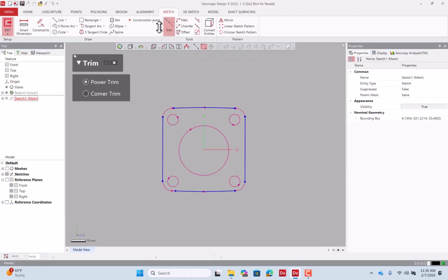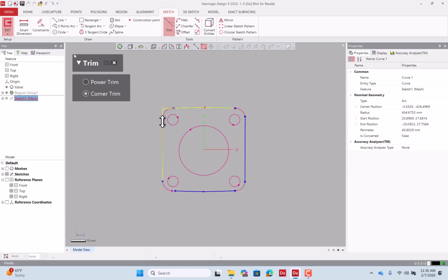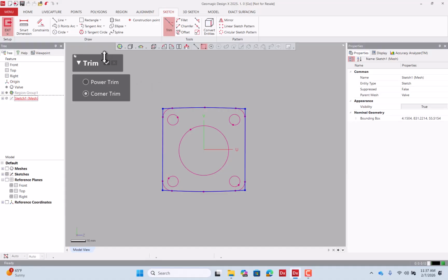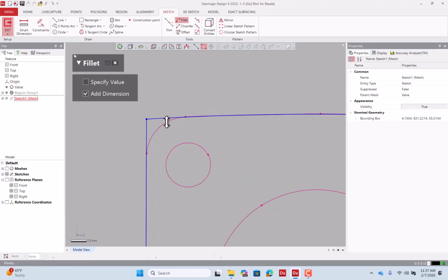We are doing this since we identified that area as a cylinder. Now you can close these edges by doing the corner trim tool. So I can click on corner trim, select my edges 1 and 2, do the same operation here again, and close out this entire structure. So I have closed out this particular piece, and if needed you can add your fillets at this stage.